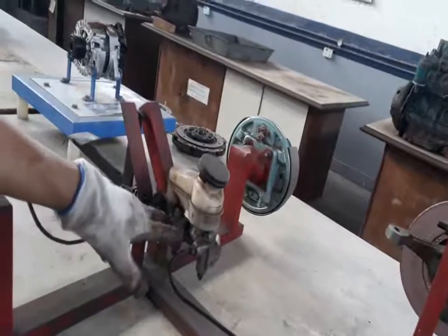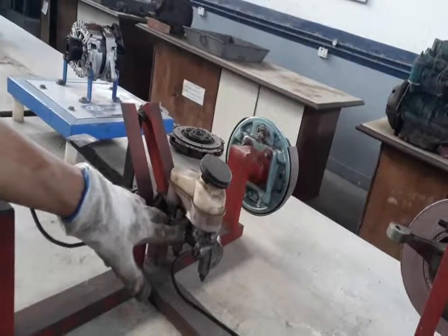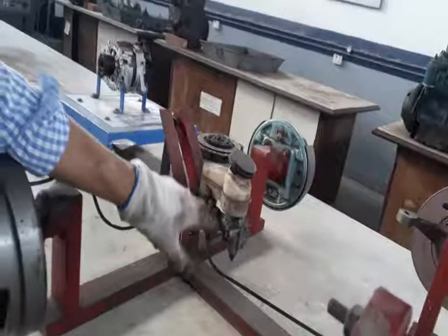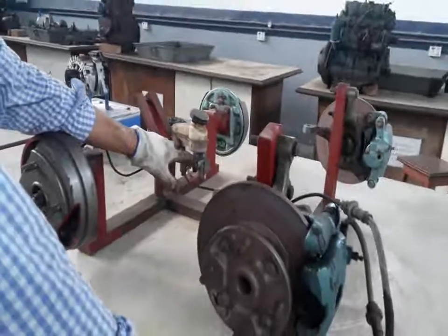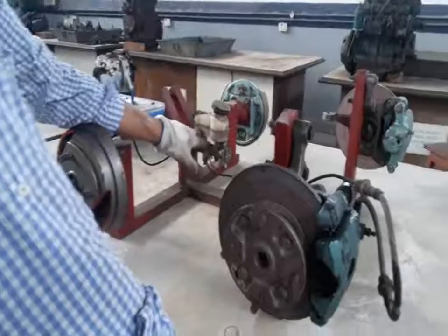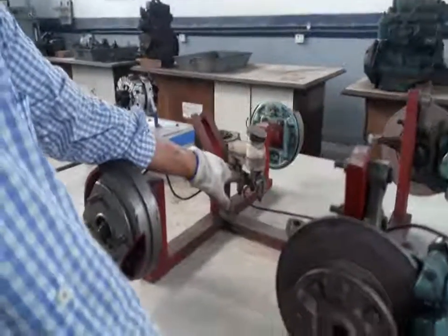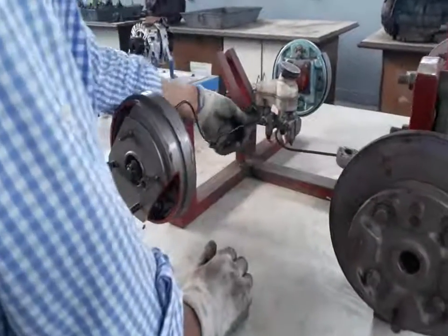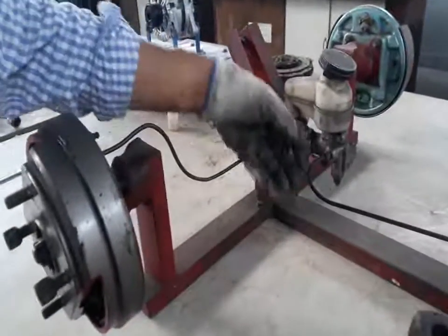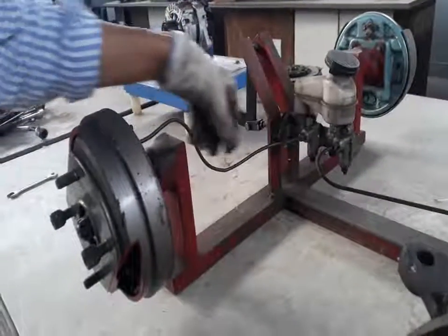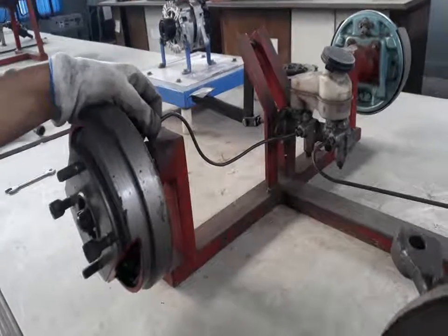There is the master cylinder which has two pistons inside. So this is called a tandem master cylinder or double piston cylinder. Between the two pistons, one primary spring and one secondary spring are placed. Okay. Now this is the outlet port, which comes from one to the front side and another comes to the rear side.